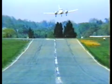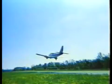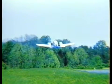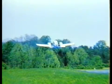Only once so far have we mentioned the practical alternative to a long landing, and that is the go-around or balked landing. A properly executed go-around is one of the best accident avoidance procedures available to pilots, even though it's one of the least used. But when it's not executed properly, it too can result in an accident, and a much more serious one than just landing long. So let's talk about how to do a go-around and how to do it right.